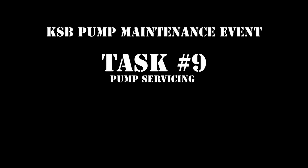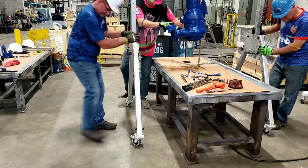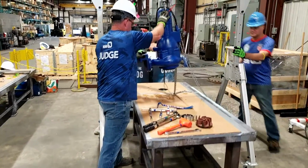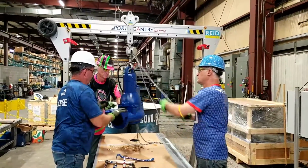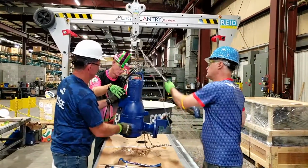KSB Pump Maintenance Event, Task 9, Pump Servicing. Once you're in position over the pump service table, lock the gantry wheels. Once the gantry wheels are locked, use the chain hoist to lower the pump to the pump service table. No tool may be in contact with the pump while it is being lowered or raised.